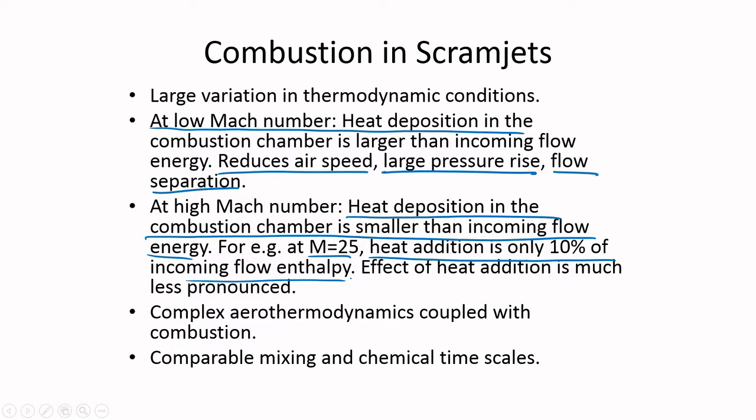The effect of heat addition is much less pronounced, but then why would you operate a scramjet engine at Mach 25 when the heat addition is only 10% of the flow enthalpy? So it's simply not worth it.